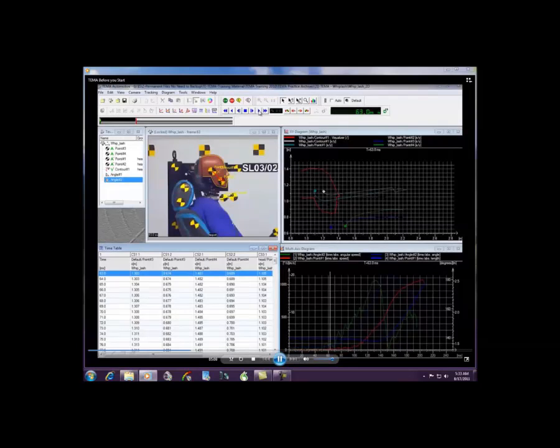This slide shows a 2-dimensional analysis of a sled test using 2 parallel planes. The first plane is the one in which the sled moves, and the second is the one in which the scaling targets on the wall behind the sled are located. The scale is set on those targets on the wall, and the distance of the sled and of those targets from the camera must be known and entered into the program so as to define the 2 planes.